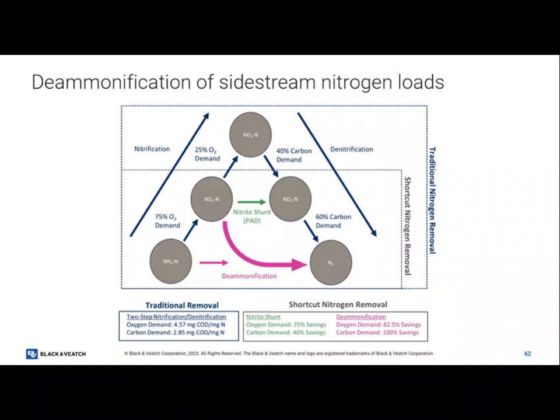well, a lot of times you're going to have almost 3 layers. So out here, you're going to have like your OHOs, your heterotrophs. They're doing maybe carbon work, and there you have AOBs. You have OHOs in here. This middle one is doing denitrification, and it's anoxic. This is aerobic. And here's where our PAOs are, in the middle. It's anaerobic.